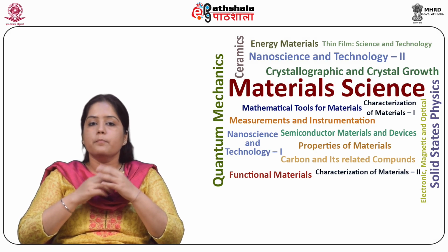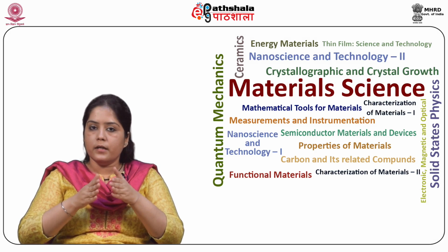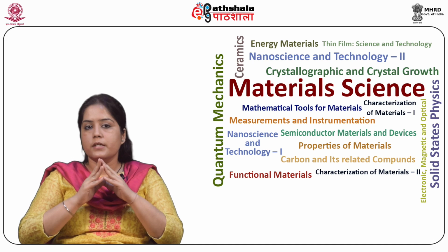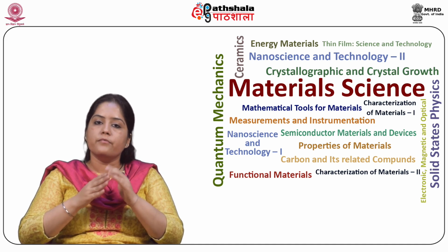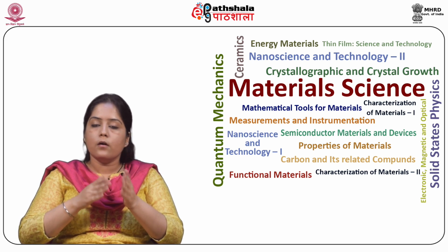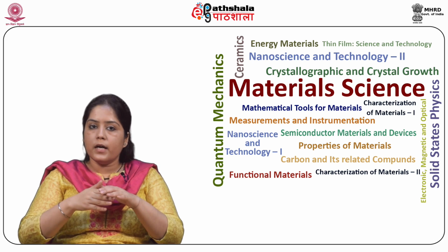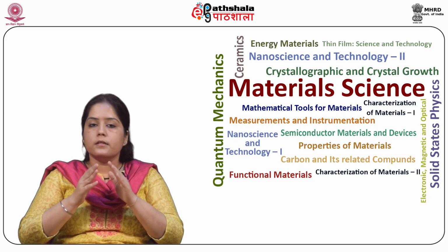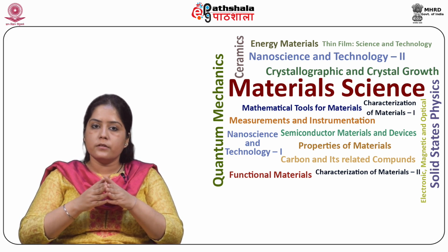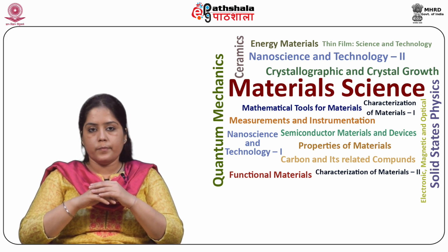Separator or membrane materials. A perfect membrane or separator material must prevent the mixing of electroactive species of the electrolyte flowing in the anolyte and catholyte sides, and the direct chemical reaction of active species can result in energy loss.